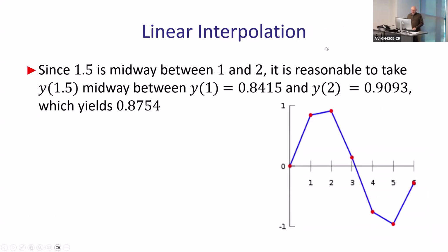So what you want to do is approximate it with basic standard types of interpolation, with standard types of functions. The most basic one is practically not even this one. It just holds the previous value. Okay? So you get to a particular point, you hold it at 0 until you get to the next point, then you jump to the next point and hold it, which gives flat lines. You're connecting the points with steps, each point connected with steps to the next, then you jump to that point, and so on. So this is the zero order hold type of approximation.